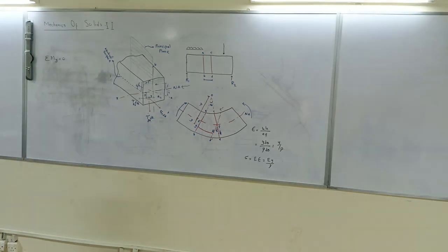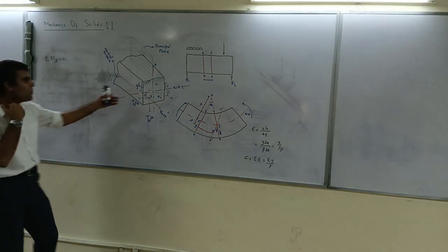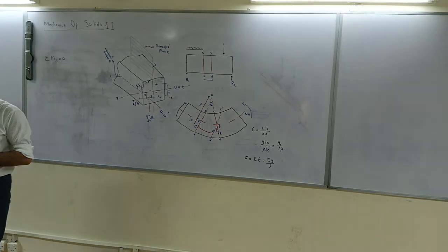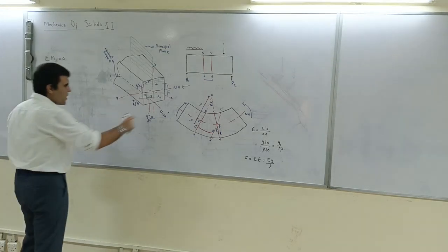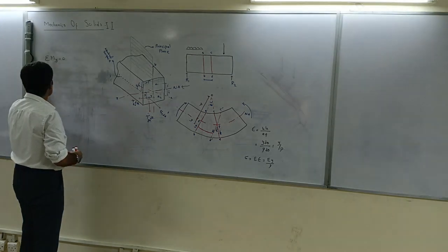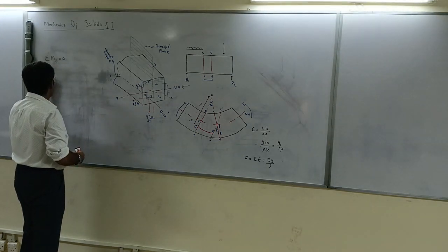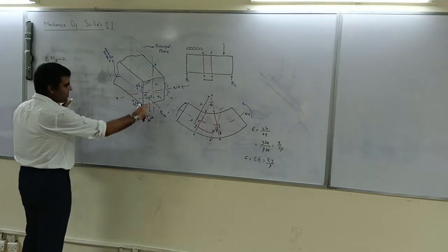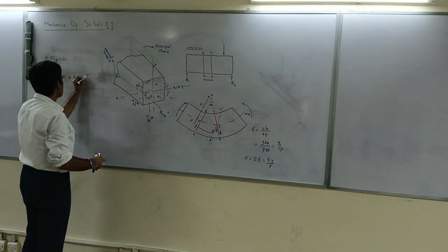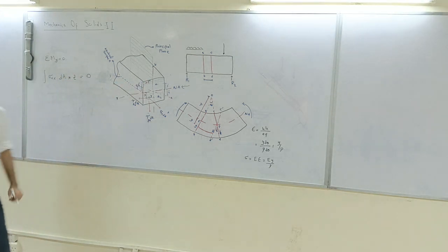That is actually the force which causes moment about the y-axis. And is there any applied moment about the y-axis? No, there is no applied moment. So let us write: stress xx times dA times z must be equal to 0, because there is no external moment.